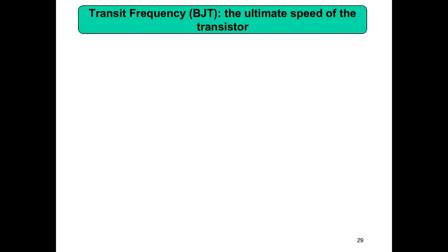Somebody gives you a transistor, maybe a MOS transistor, and then asks you two questions. What is the maximum gain you can get? What is the maximum frequency you can operate? You should be able to answer these two. The maximum gain you can get, which we already studied, is called intrinsic gain, which is equal to minus GM into RO. That is for a common source amplifier. You can't say, oh, depending upon all the design, no, that's not correct. The intrinsic gain is minus GM into RO.